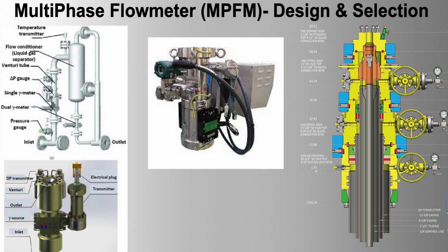Practical examples of usefulness at the central facility. 1. Production balancing. Scenario: the central facility receives varying amounts of oil, gas, and water from different well clusters. Without MPFMs, it's challenging to predict and manage these variations. Benefit: MPFMs provide real-time data, allowing operators to adjust the processing rates and optimize separator performance, ensuring smooth operations and maximizing throughput.